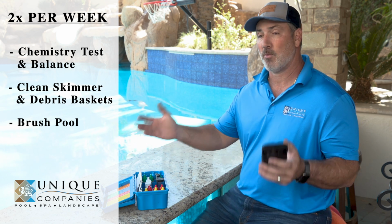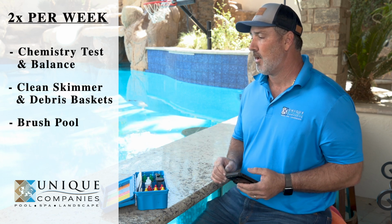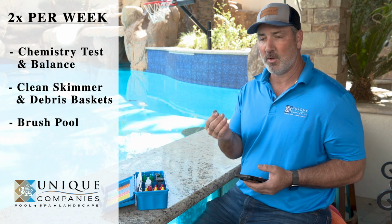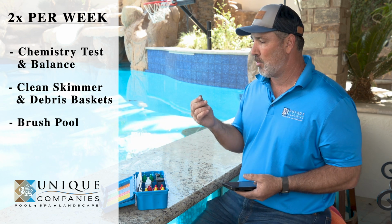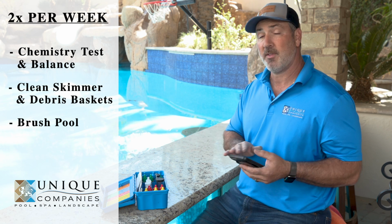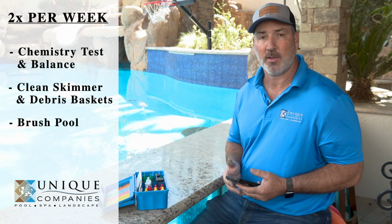In fact, we put that in writing in our construction agreements. Just because new pools, they're fresh, the fresh plaster, any dirt that gets in that pool could actually bind to the plaster and you can start to see stains. So brushing that dirt off the top, it brushes some of the Portland cement residue off the aggregate, and it gives you a brighter, cleaner looking finish.